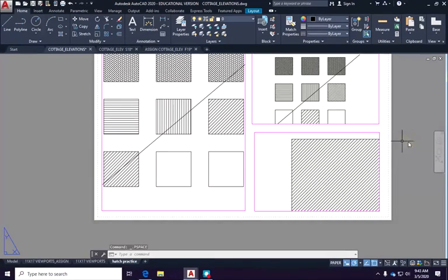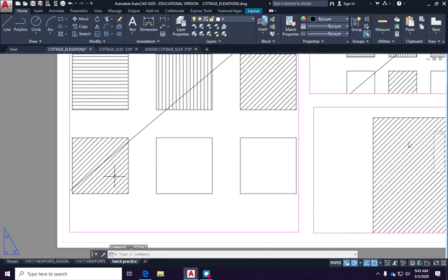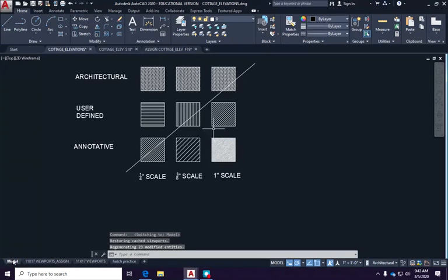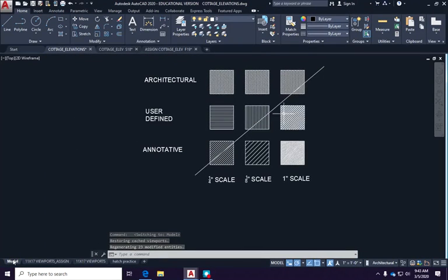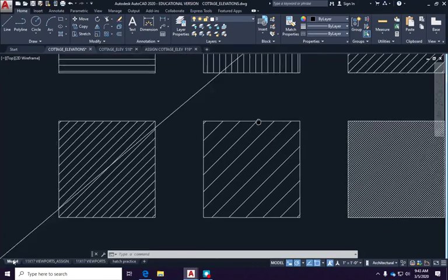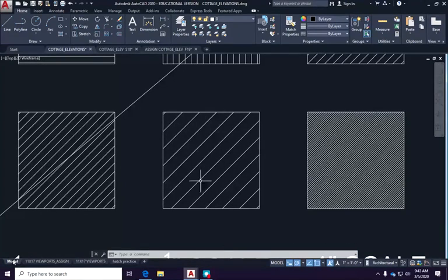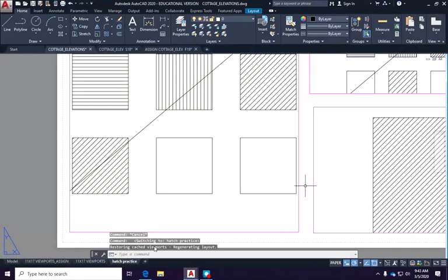Now the really weird thing is if you zoom in, and you took a scale and measured the distance between these lines and these lines and these lines, they are all the same distance apart. It's because that's the type of hatch civil engineers, structural engineers, those people use. So when you go back to model space, everybody looks the same up here, but when you get down here, they're completely different sizes. But when you go into your viewports, these 3 guys are all the same size.